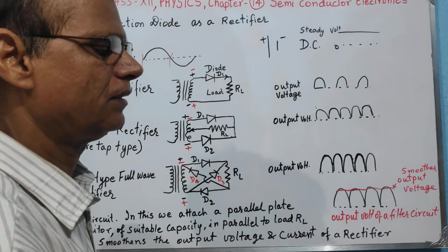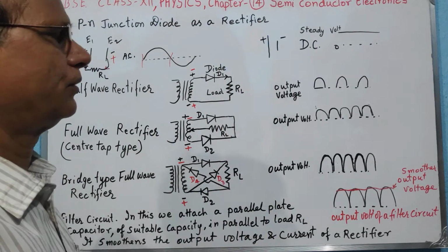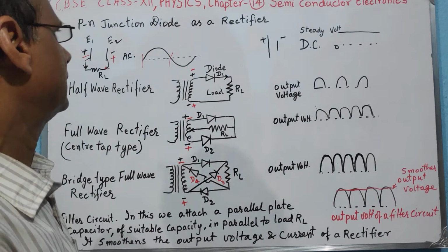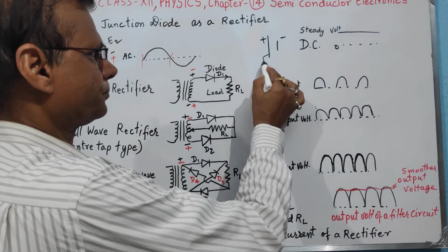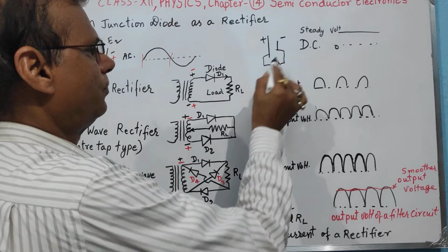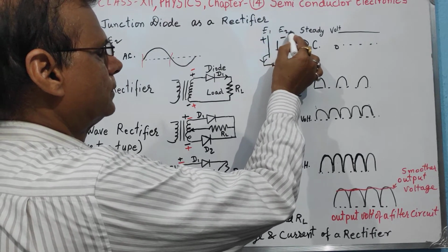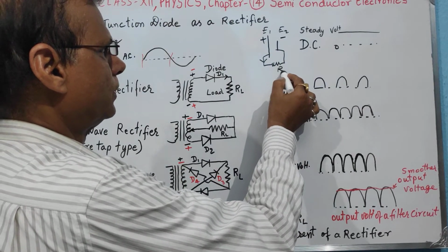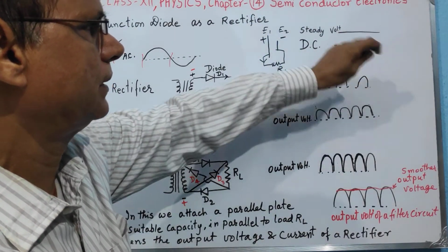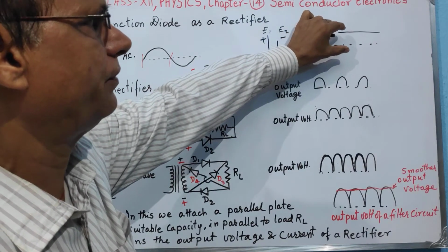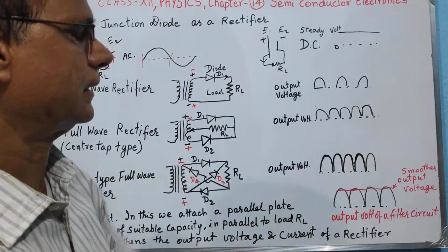In case of DC, say we talk about a simple Leclanche cell or any dry cell, one electrode always remains at high voltage, and the other electrode always remains at low voltage. Therefore, if we connect a load to it, the flow of current will always be from the first terminal E1 towards the second terminal E2 through the load. That is displayed by this picture, in which a fixed or nearly fixed voltage is applied across the load, always in one direction.